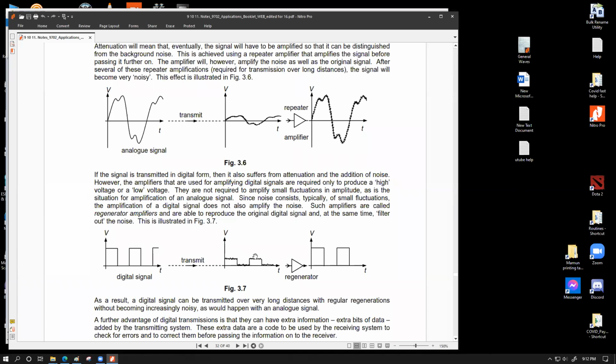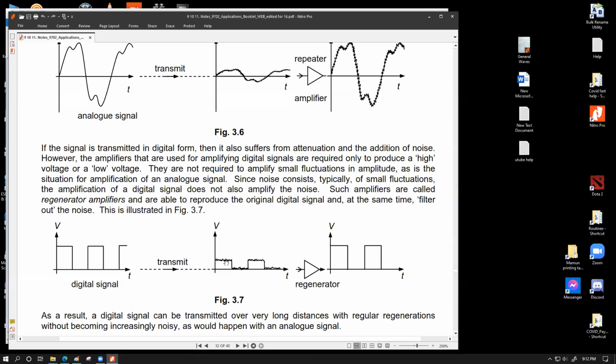You might wonder why there is zigzag only on the horizontal lines and not on the vertical lines. You have to understand, these vertical lines represent zero time, the time instance where the voltage changed from 1 to 0. So you cannot have a horizontal zigzag. That would be going back in time. So it's actually not logical. So this is just a basic variation. The same thing is happening over here. All the values of the voltages are picking up noise, and we have the ones and zeros.